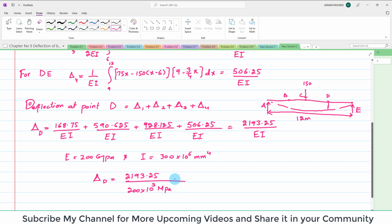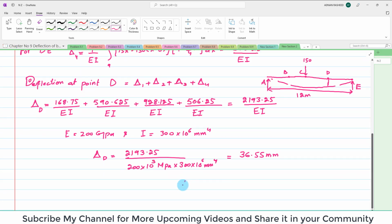And we will have 300 into 10 to the power 6 millimeter 4. When you solve this, you will get 36.55 millimeter, or you can say delta D is equal to 3.65 centimeter. So this is the deflection at point D.